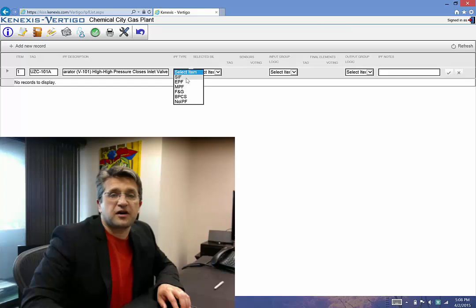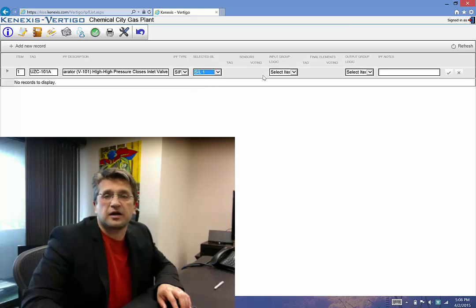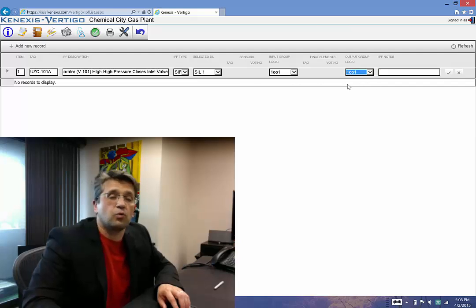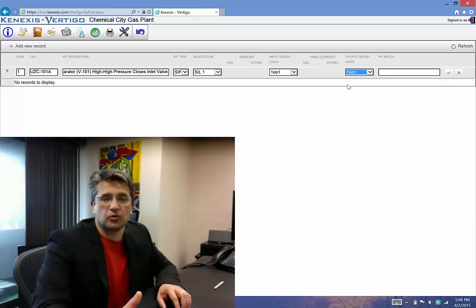Okay, the IPF type is going to be safety instrumented function, but you have a range of different IPF types that you have available for sorting and nomenclature purposes, and we said that we were going to assign SIL 1 at this point in time. The other items that you're going to define here include the IPF group voting logic, which most of the time for both inputs and outputs is going to be 1 out of 1, meaning that we have one measurement group.